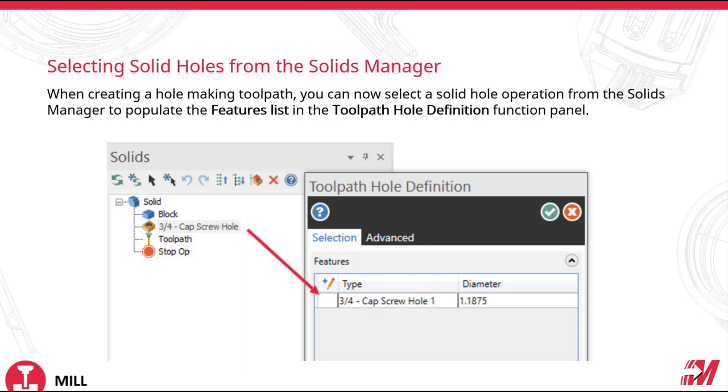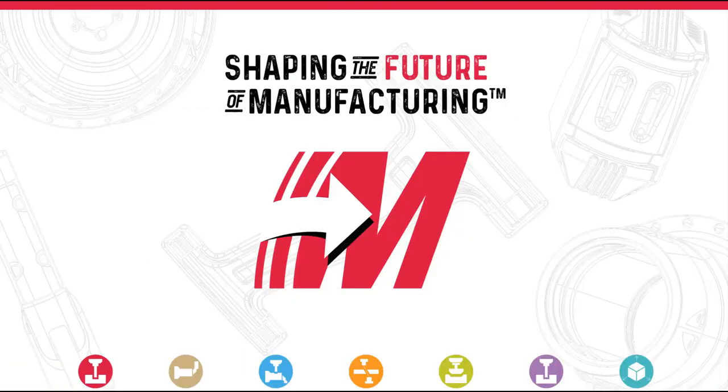So once again, it's just trying to automate that for you, so you don't have to do as much work on the front end analyzing anything. This is going to give you your diameters, your depths, and any clearance values to leap over solids automatically. So they made a lot of strides with drilling in Mastercam that we can take a look at. And we'll take a look at that next on a bunch of examples and part files.